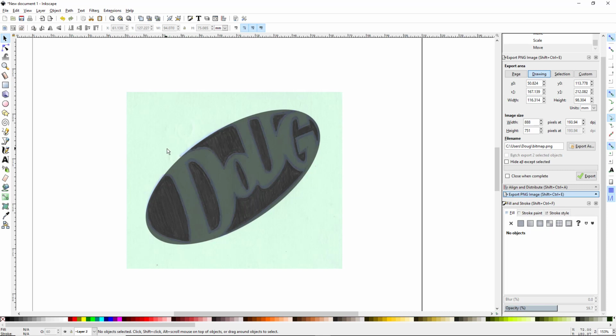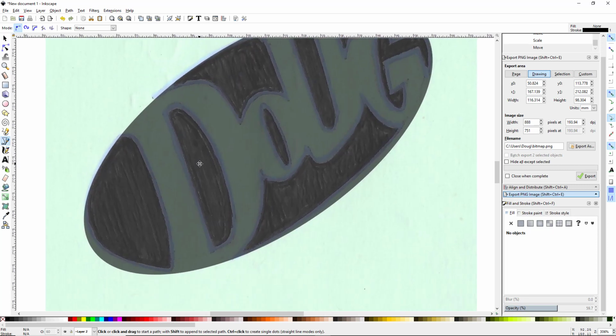We're going to grab our Bezier pen by hitting B on the keyboard, or coming over here and clicking on this blue pen over here. And what we want to do is make sure that our snapping is enabled. If you go over here, you see enable snapping. That will be highlighted in blue. And then you want to make sure this one, snap to paths, is selected. And that will allow you to click exactly on the edge of this ellipse that we created.